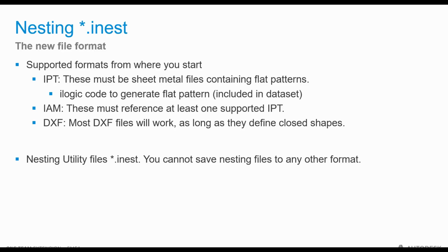So you could have multiple files that would be STEP files or CATIA files or something like that, you could actually bring into the assembly environment, and as long as it has one supported IPT, you can convert the whole assembly into a nest. Again, DXF files, you're easily able to import them and use them as long as they're closed shapes.